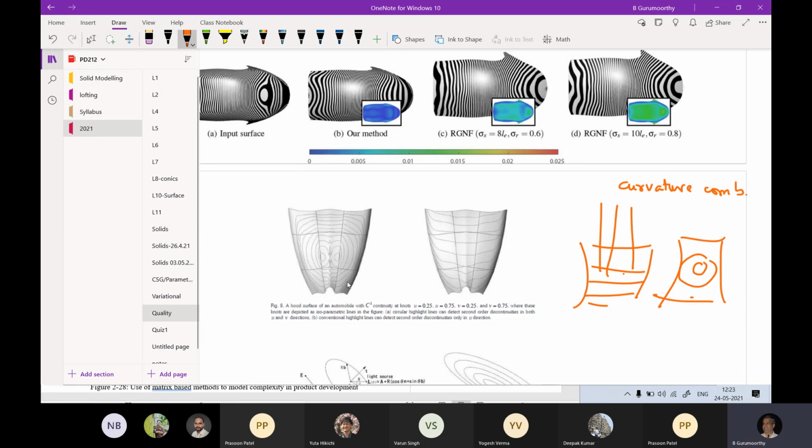And immediately you can see where I have local kinks and breaks in the surface, undulations that I have not anticipated. I may have a crease in the middle of the hood here, so I do expect to see a break, but I don't expect to see a kink like that. So I need to go back and do something about that.